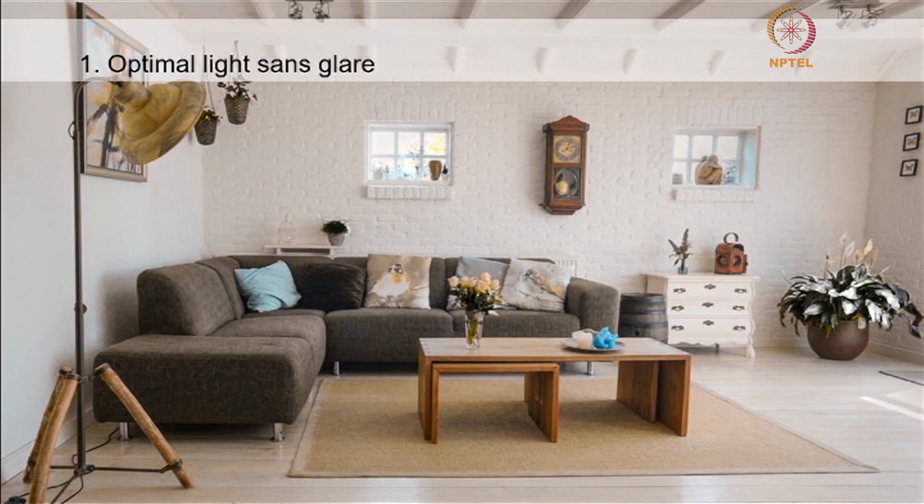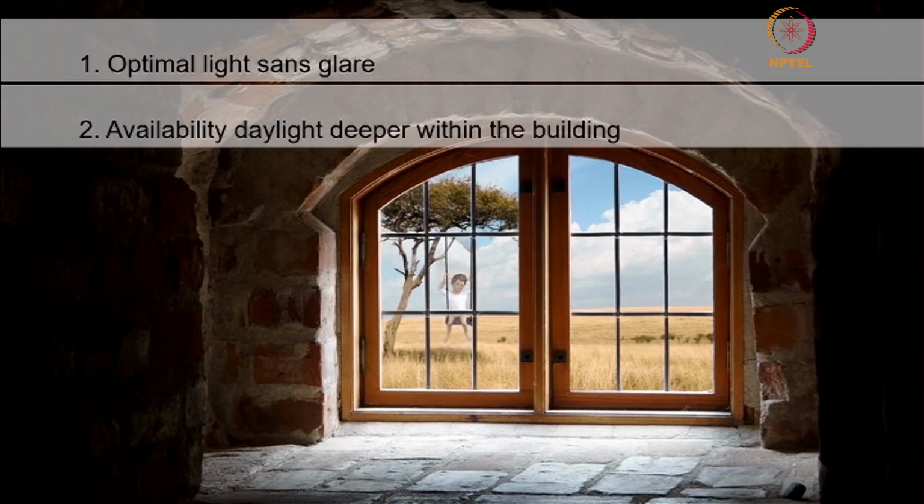So, the first objective is to have optimal lighting without glare. We can derive an apt solution for any given problem if we have a clear idea of the intent. So, here the goal is to have sufficient amount of high quality light without glare, number 1. Number 2, to get enough daylight into the deeper areas, since typically there is too little light at the back of the room and too much near the windows or on the facade of the building.